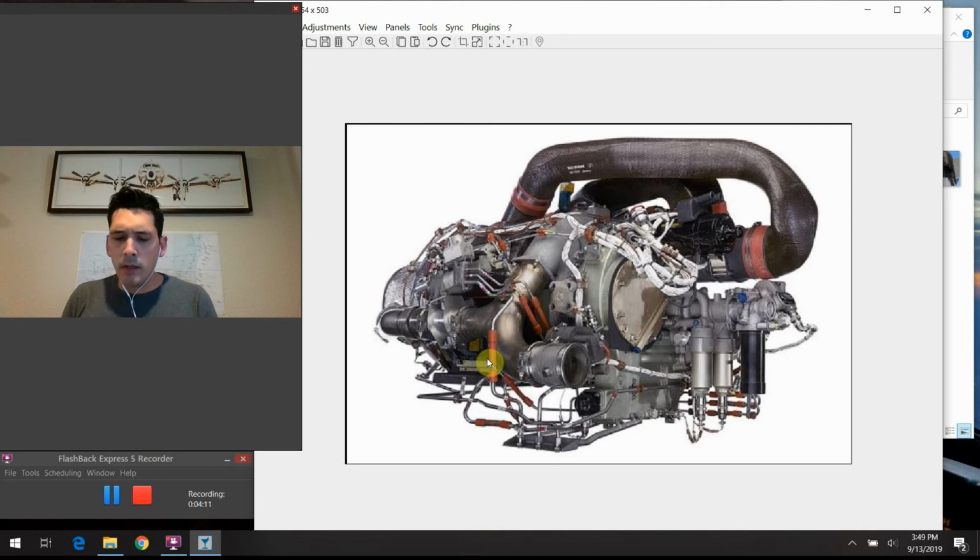So like I said, along with this application of the use of the APU engines in the airplane, of course, came an enhanced level of redundancy, in the form that once again we have several systems in the airplane that need the air power and the electrical power. It's just kind of a nice thing to have if we're flying around and one of the main engines goes down for any reason, or even components of the main engine get taken offline.